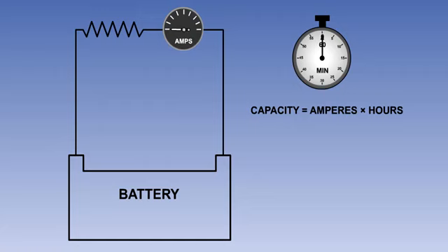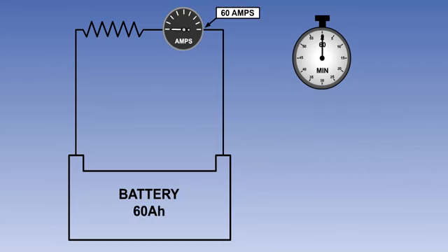As we have already said, the capacity of a battery is the product of the load in amperes that the manufacturers state it will deliver, and the time in hours that the battery is capable of supplying that load. The capacity is measured in ampere hours. Actual capacity is determined by the battery's deterioration in service.